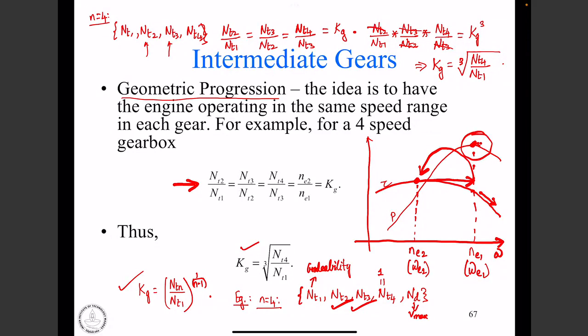Imagine we are past this point, and torque reduces, and then we are going on a road, and suddenly we have a slight upgrade. Just let's picturize that scenario. What is going to happen? The speed will naturally fall down. Why? Because the load torque is now increasing, right? Although I may be in the highest gear, I can press the throttle, but the vehicle will progressively slow down unless I downshift to a lower gear. Then engine speed will also change.